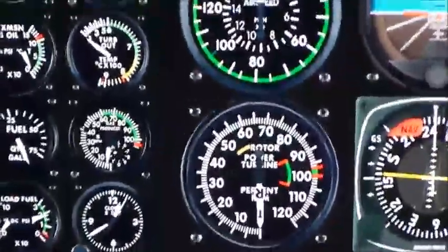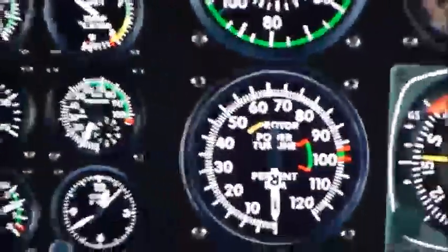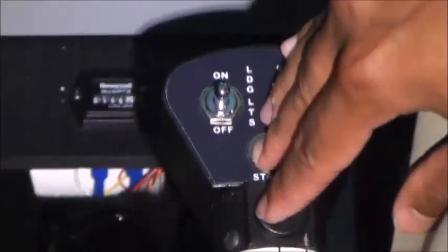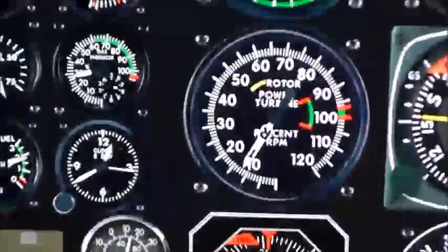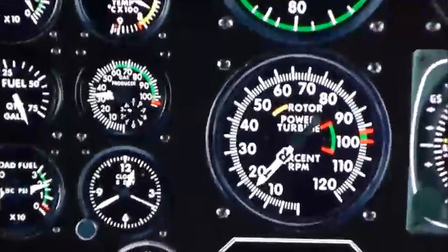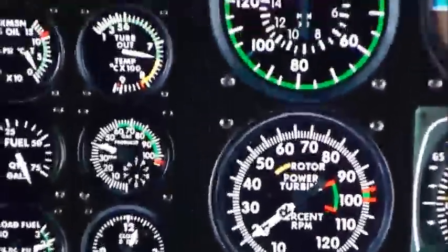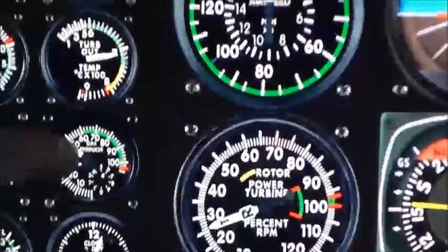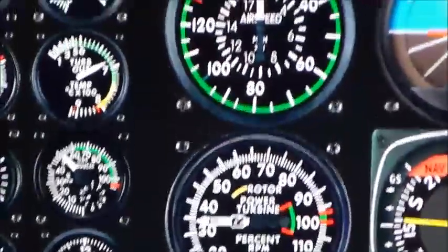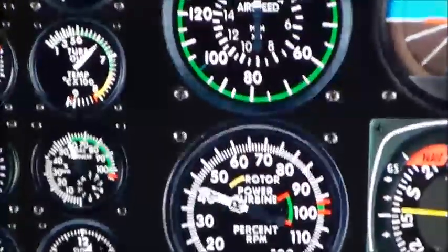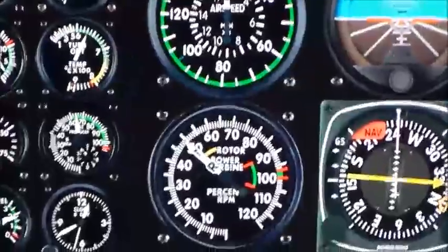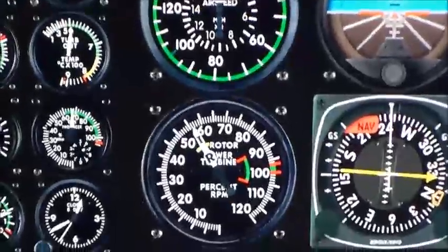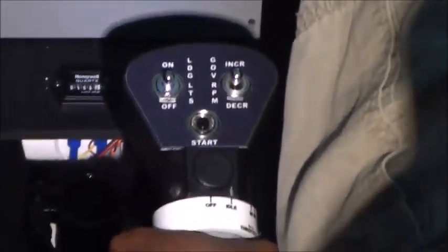All right, so let's start the timing from here. So I've got the timing. We're watching the TOT. There's the TOT. My rotor is spinning already. Okay, so I'm going to hold the gas reducer until we get to 60%. We're looking for 60% here. There we go. Okay, there we got our 60%. The starter is released. And throttle increase to flight idle. Okay. Check.